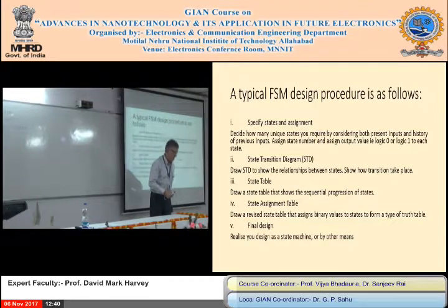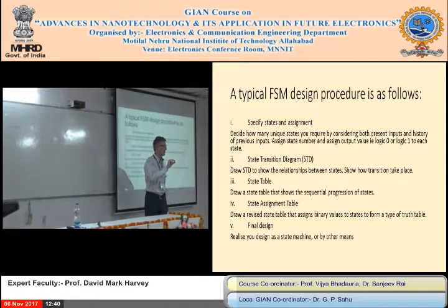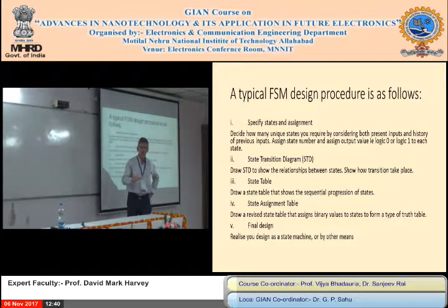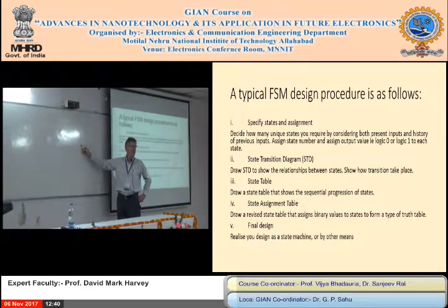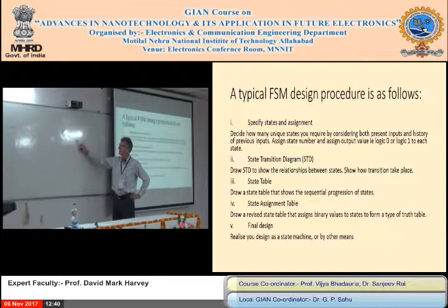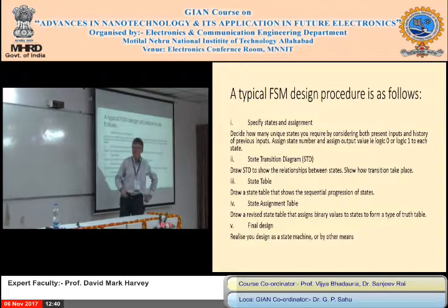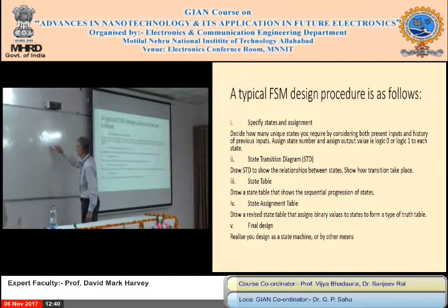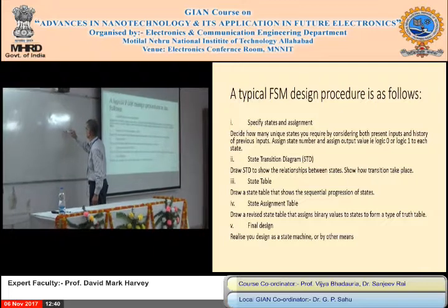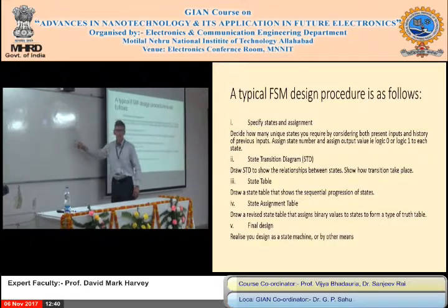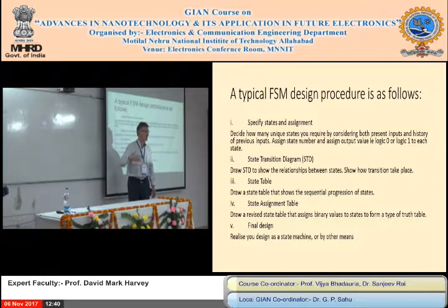The normal definition of parity is the number of logic ones in a sequence. So if you've got 0, 0, 1, 0, 1, that's 1, 2, so you've got an even number of ones, that's even parity. If we do another sequence, 0, 0, 1, 1, 1, that's got an odd number of ones, so that's odd parity.